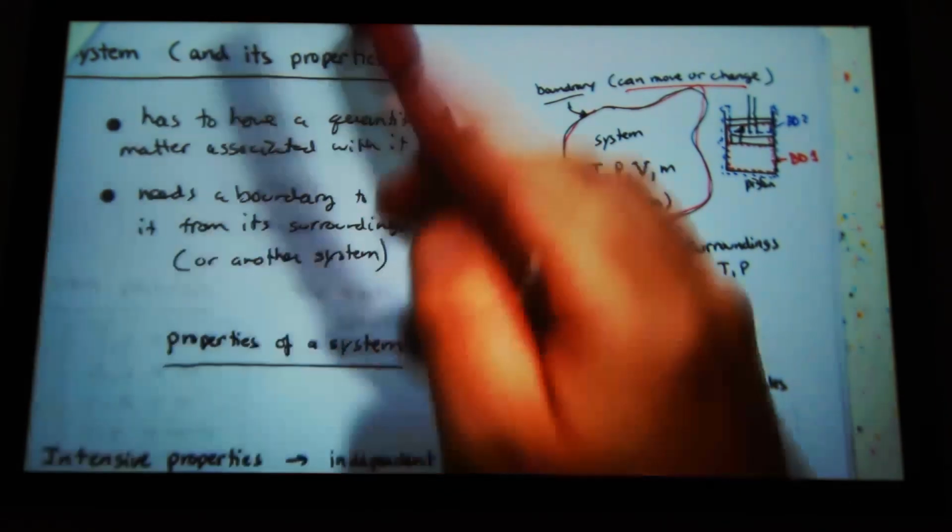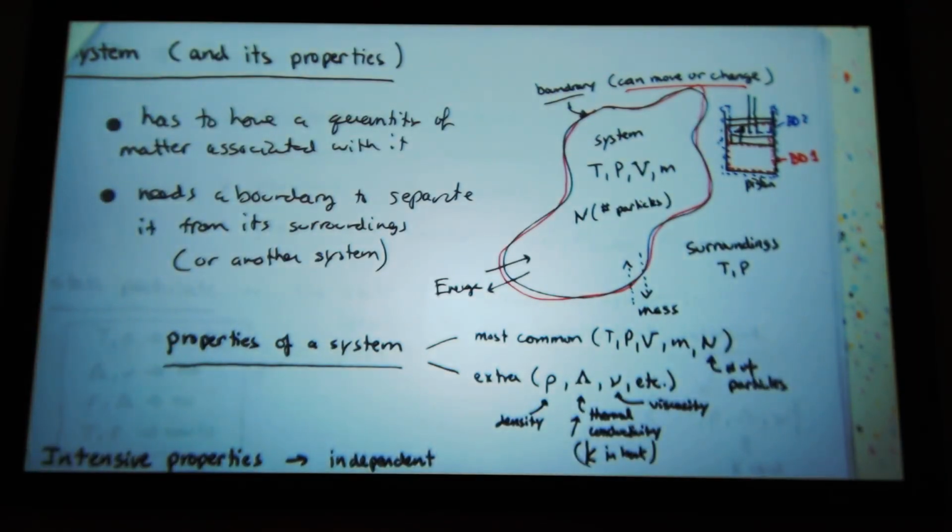So, yes? For boundary 2, I understand for boundary 1, the work being done by the system is on the piston going up. But for boundary 2, what is the work being done by the system? Well, it's the same. So it's still on the piston itself? Yeah, well, all I did is displace the stainless steel. But if I don't have thermal expansion of the stainless steel during a power stroke, then the stainless steel part of the system didn't do work on the surroundings. So typically you have an engine, it operates, it heats up, there's expansion of your engine. So really that small amount of expansion of your engine during heating up is doing work on the surroundings.